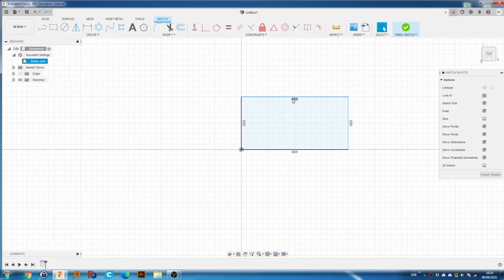scaled, for example. So this knows that it should start at the origin because it's got a coincident constraint. So if we go on here, you can see this is the same shape as that, coincident, which means it meets there, it connects, it touches, something like that. Coincident means that line is meeting that line. But these are blue, so we never want to leave it. And I must admit, sometimes if I'm doing something extremely simple and I'm extremely lazy, I leave it blue, which is not a good thing to do.